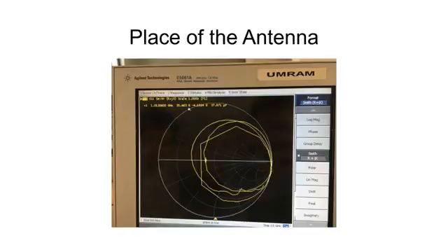If I match this resistance with the signal generator resistance, I will decrease the attenuation in my cavity, and it will be a matched circuit, and we can easily see the behavior of the cavity without these effects.